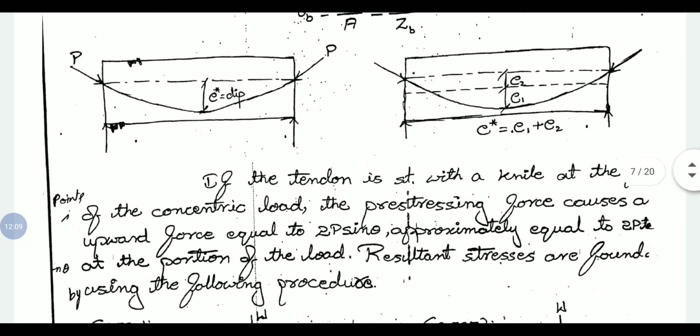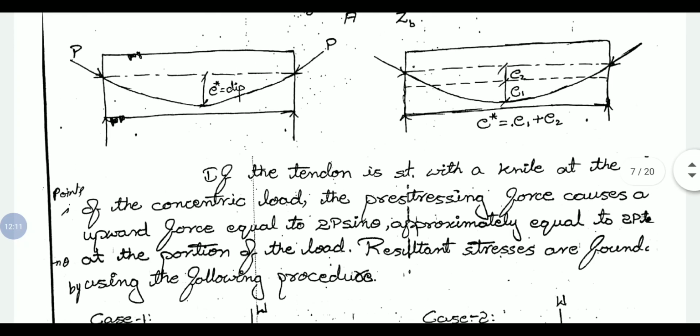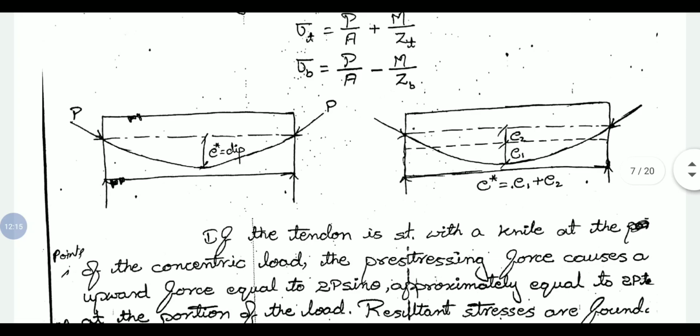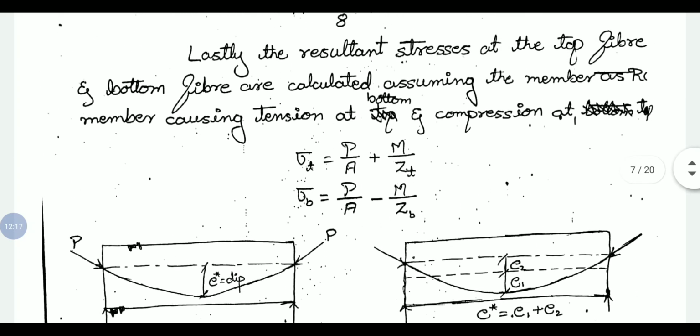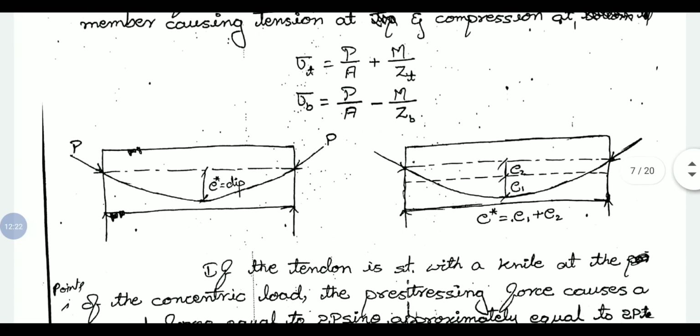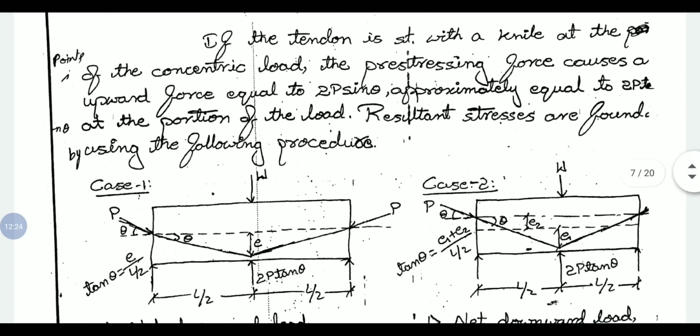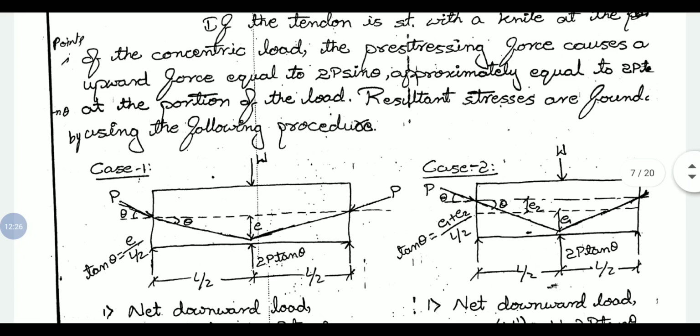So for those two cases, we can use the formulas, and for calculation of moment we have the formula on the last page. Here we have one more case, when we provide a straight cable with an angle at the midspan, or visually we can say a triangular profile.